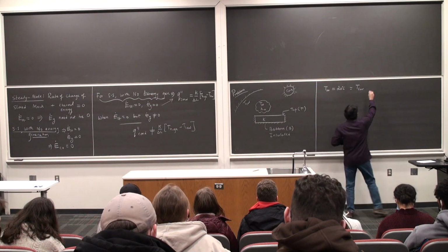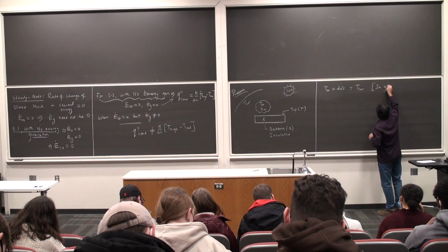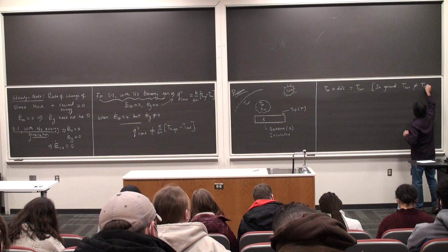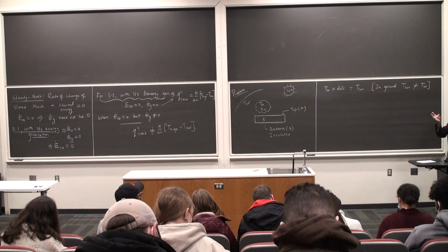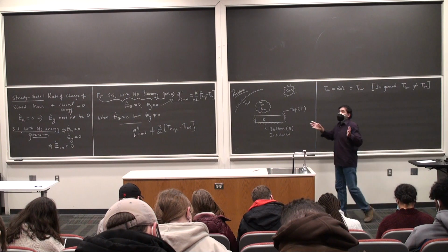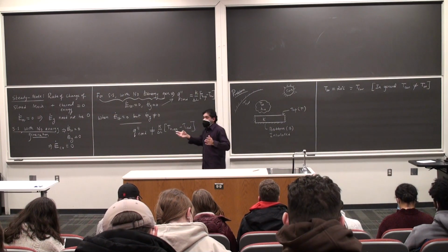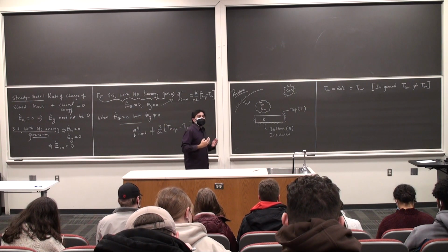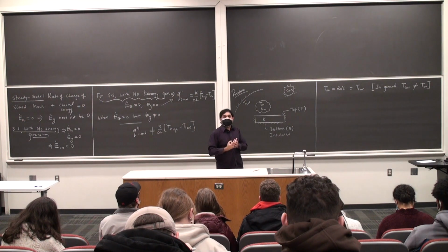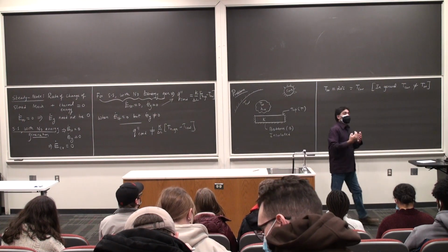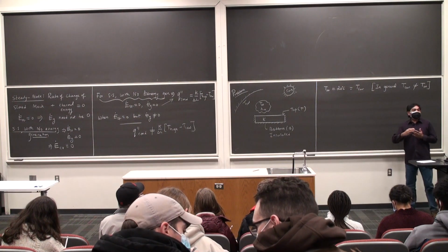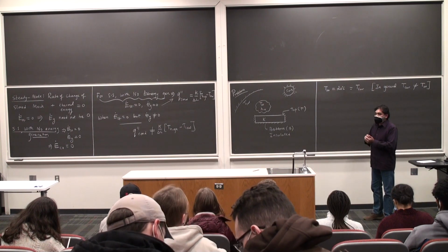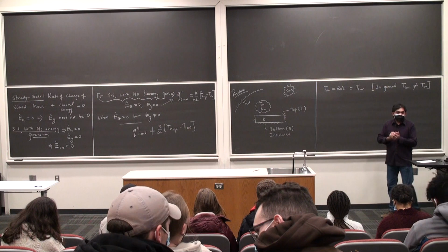So this is not in general true. In situations where you have a surrounding temperature and you're not told any information about it, then you can assume that, unless I'm asked to find out what it is from the balance equations, I can assume it to be the same as the temperature of the ambient fluid, only in such situations. So it is very important that you list out all your assumptions carefully and go over them to see if there are any inconsistencies, which will get caught when you solve the problem. If you get some funky numbers, it's probably something wrong with the assumptions.